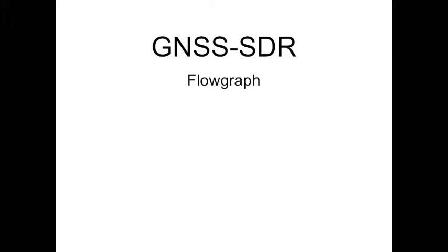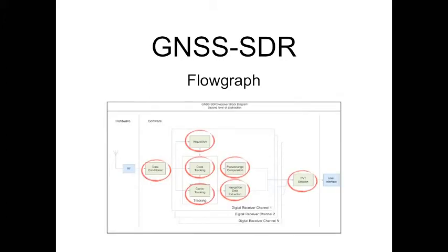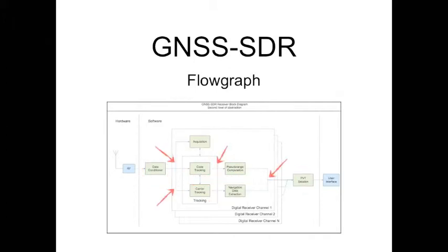An SDR application that follows the channel architecture pattern can define an almost infinite number of flow graphs, but in our case we wanted to implement the model of a GNSS receiver. That model has a specific form and a specific number of parameters that can be applied to it. So, for instance, we know we need instances of specific modules: data conditioner, GNSS channels, PVT, output filter. Connections between modules are always the same.